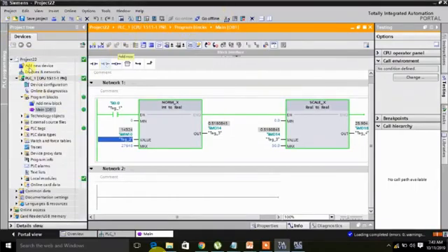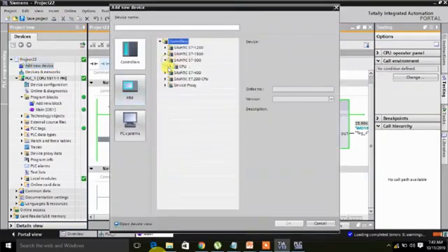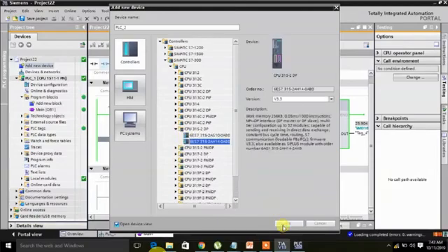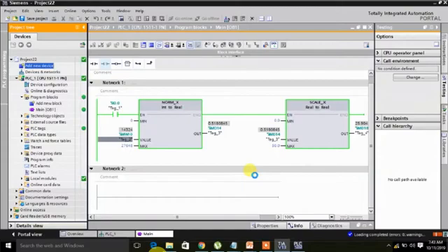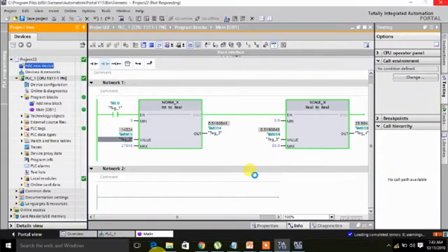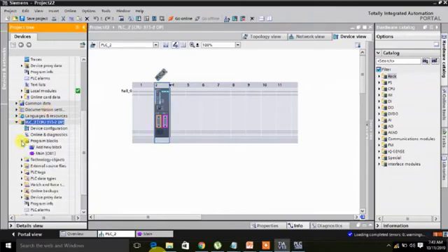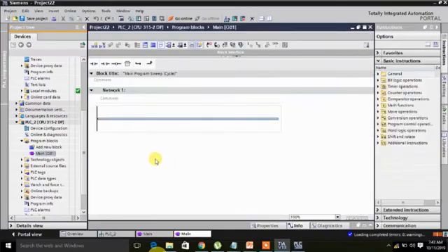Now we will add a new device, S7-300. Any S7-300 you can use. We will add it here. Actually the 300 and 400 are very simple, so you can easily scale and convert it. There is no need to add NORM_X, you need to add the scale block and you can do the conversion. If you don't have any conversion available, you also need to calculate it. For this calculation I also made one video on how to convert and calculate it. You can calculate it very easily.